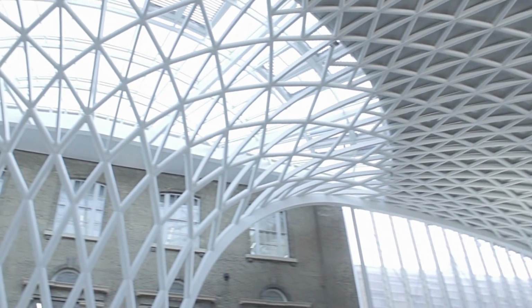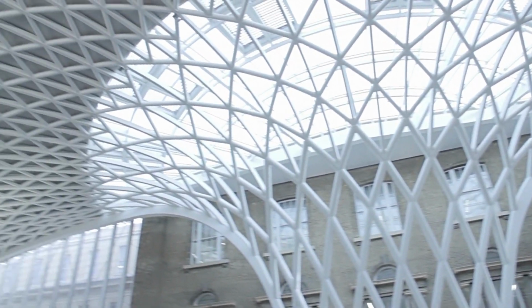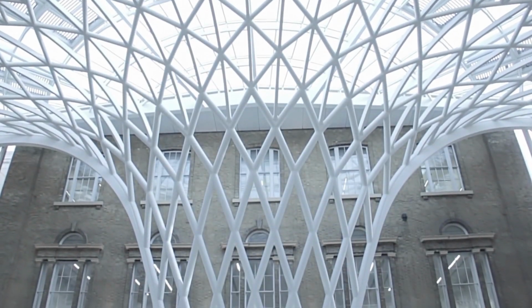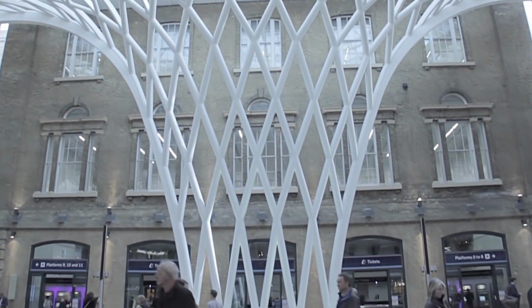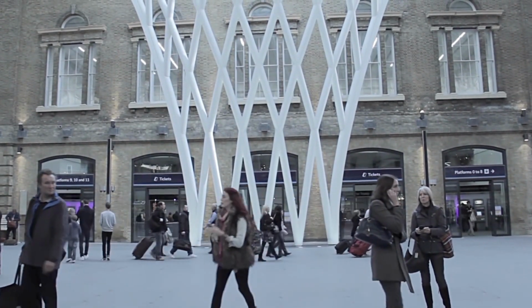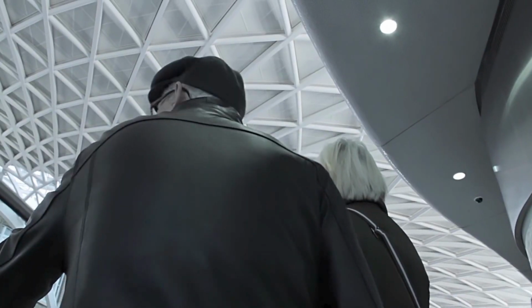3. Water efficiency. Implementing measures to conserve and manage water resources effectively. This includes installing water-saving fixtures and appliances, incorporating rainwater harvesting and greywater recycling systems, utilizing drought-resistant landscaping, and designing efficient irrigation systems to minimize water consumption both indoors and outdoors.